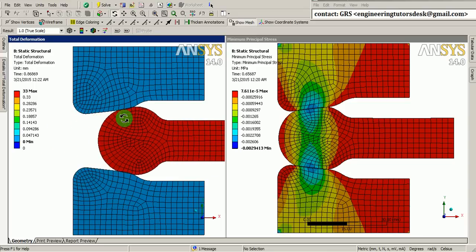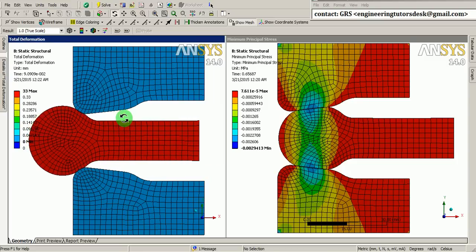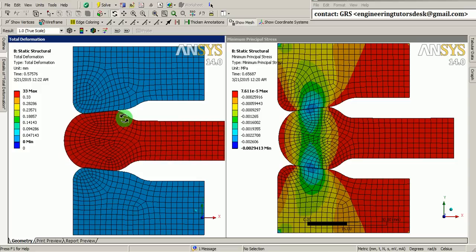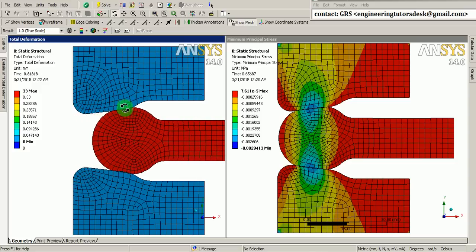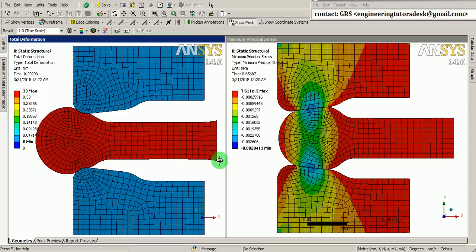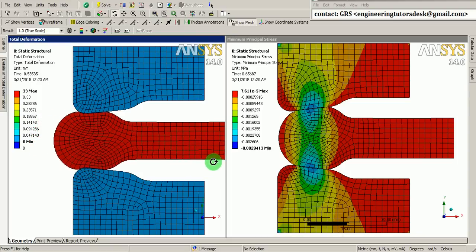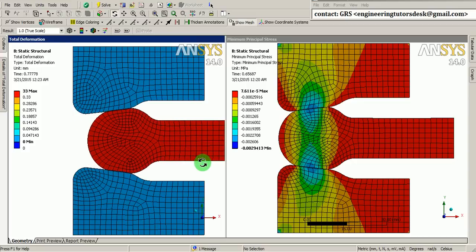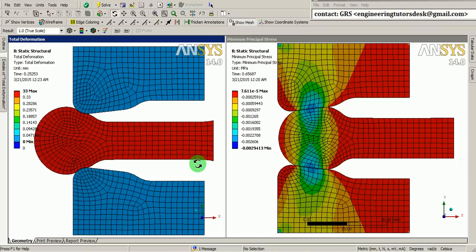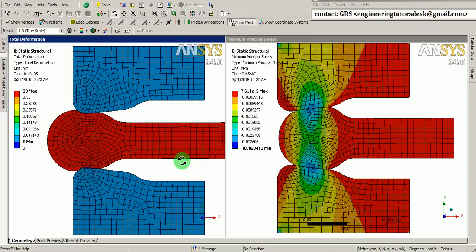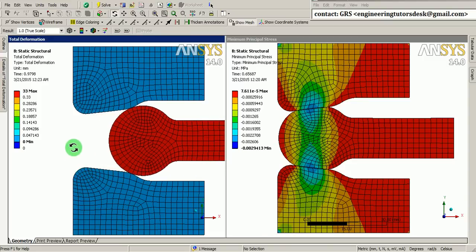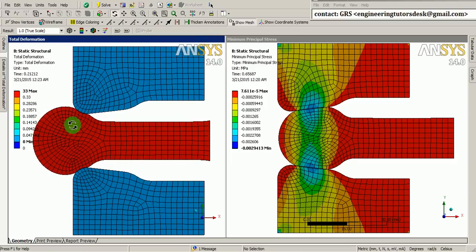This behavior can be observed for a material like rubber. To model this behavior, there are different material models. One of the material models to model such a behavior is the Mooney Rivlin material model. Let us understand how to define the parameters of Mooney Rivlin in ANSYS Workbench to predict the behavior of hyperelasticity for the materials.